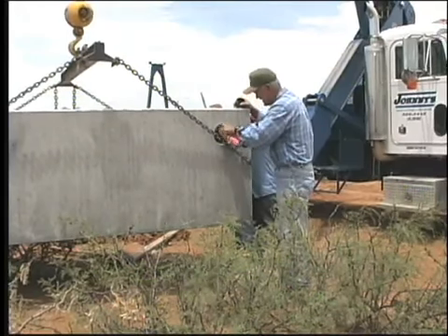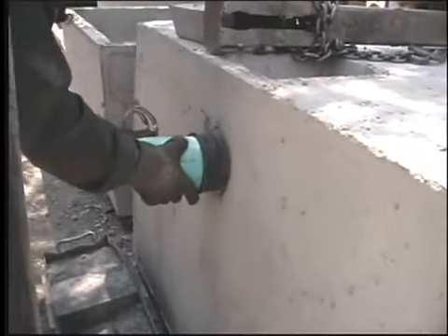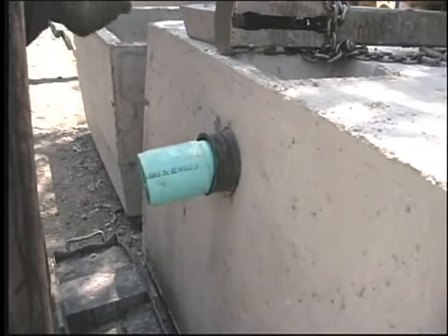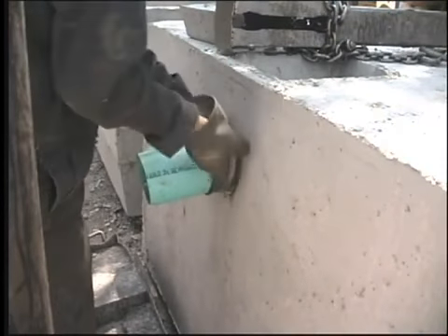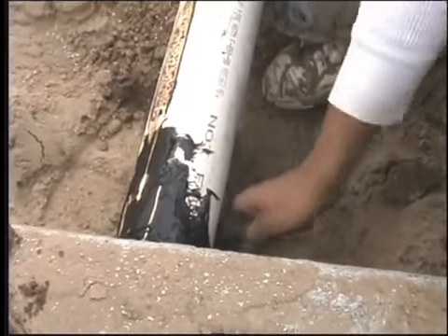You may wish to improve the seal on some collars by clamping the collar to the pipe using a large hose clamp. If the tank has a large diameter hole for the inlet and outlet pipes, these holes must be sealed after the pipe is inserted. Use grout, mortar, or a bituminous sealant such as mastic.